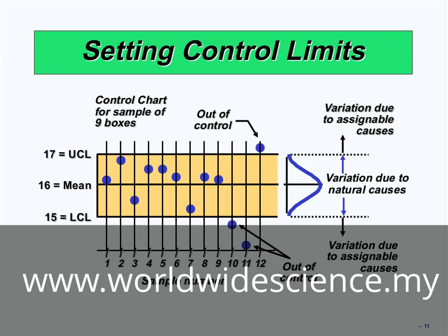It's the standard. It has been defined earlier and you should follow it. If you want to use the X bar chart, you should follow this process. At first, you should select the population at a regular time, half an hour to half an hour. When you select the population and take them to the laboratory, we should measure the X.